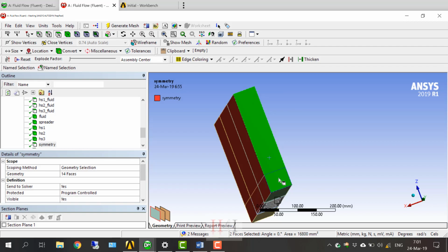Because if the pressure of the water is higher than the ambient pressure, this means the flow is coming very strong, so its velocity increases further because there is no equilibrium at this surface. To achieve equilibrium, the flow will keep increasing its speed until its pressure adjusts itself to be the same as the ambient pressure. So the flow comes outside of the pipe in an equilibrium state.